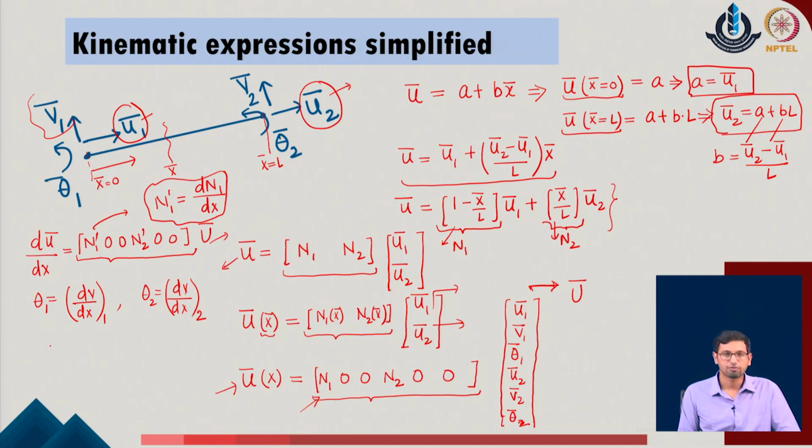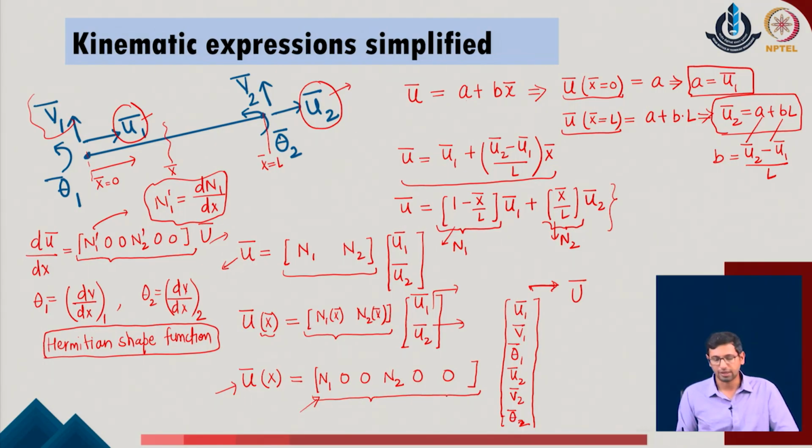Typically, in the standard finite element expression, we come up with something called Hermitian shape functions, which we use for this case. We are not doing this derivation again in this process, but one can easily refer to any standard text on the finite element and get the Hermitian shape functions for this part. The one which I have derived here, these are the simplified Lagrangian shape functions for the linear element. When we have only two nodal values identified, we can describe it by the linear function. Similarly, the process is very simplified. One can easily describe the variation of the v in terms of the standard function, which now has 4 values, because you have v1, theta 1, v2, theta 2, 4 values in the system.